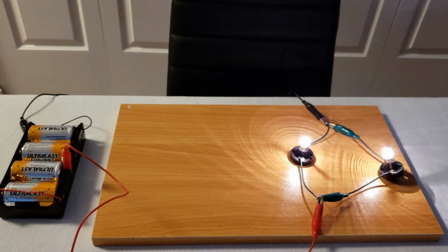The reason for this is because both light bulbs are connected directly across the source. They both have 3 volts across each light bulb. As a result, the same amount of current is flowing through these two identical light bulbs. And that's why when you connect light bulbs in parallel with each other, the brightness is the same. It doesn't reduce because the voltage across each light bulb is the same, which will induce the same amount of current, assuming the two resistances are the same for each light bulb.